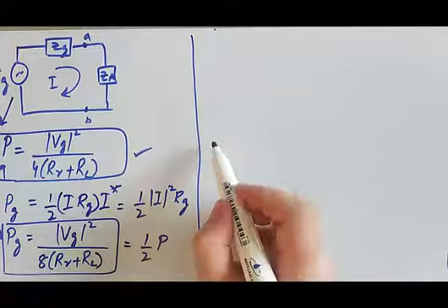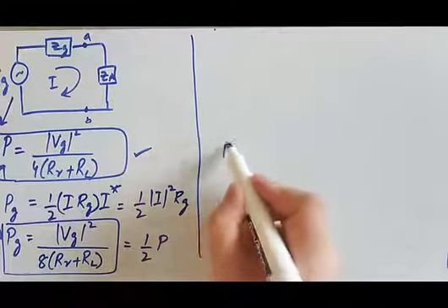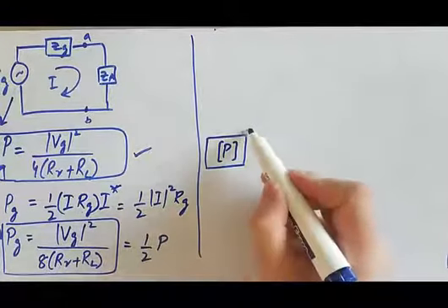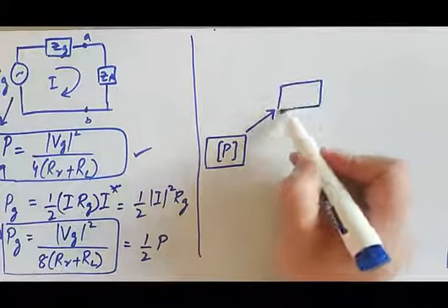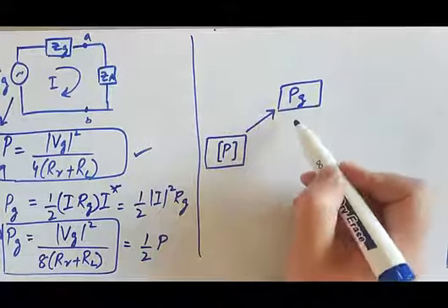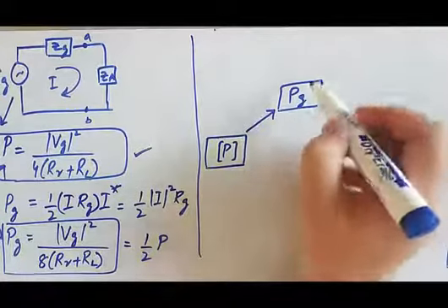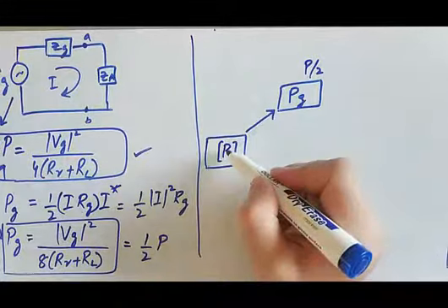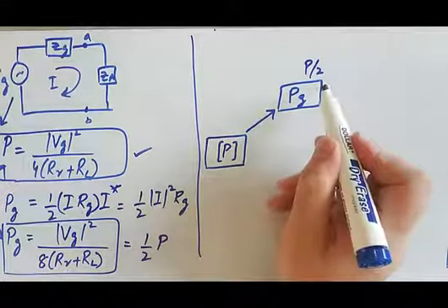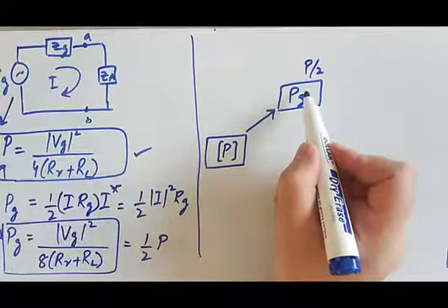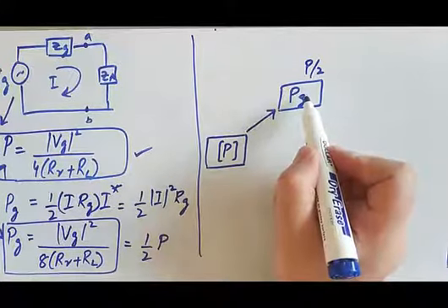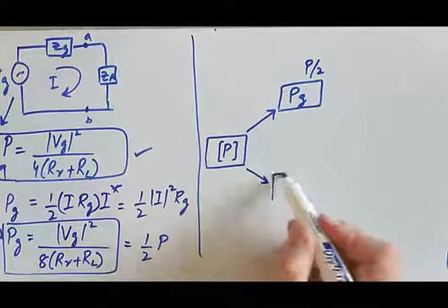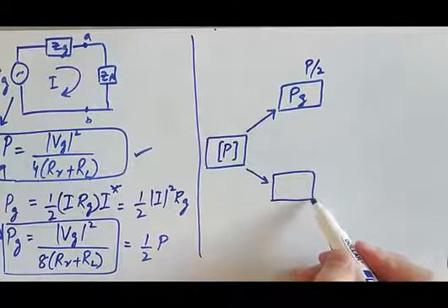powers being calculated. So let me say the power available from the source, let it be P, okay, and then half of this is dissipated in the generator resistance. So this is actually P/2, in fact. This was the P we got that is available from the generator, and then half of it is dissipated in the generator resistance. And then if you notice, we also calculated,